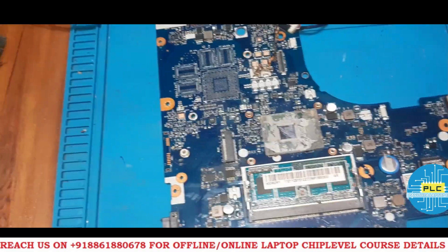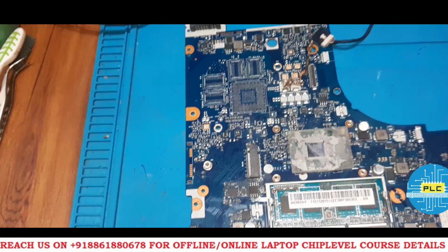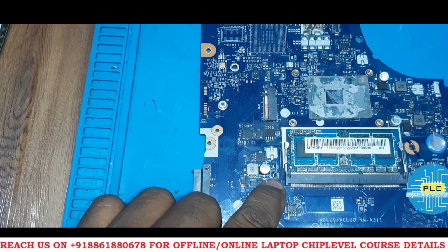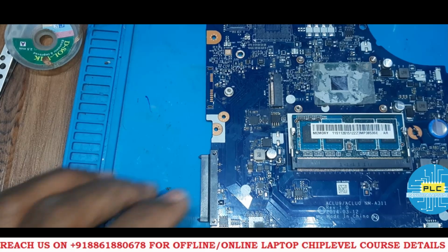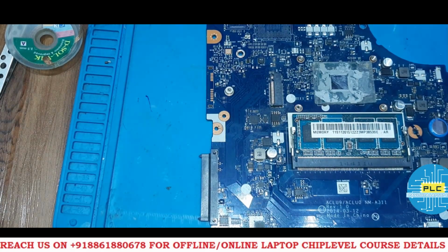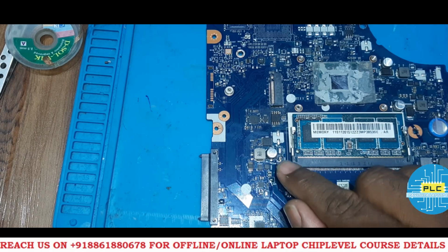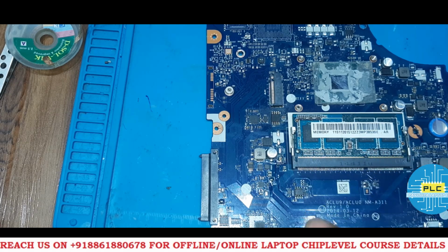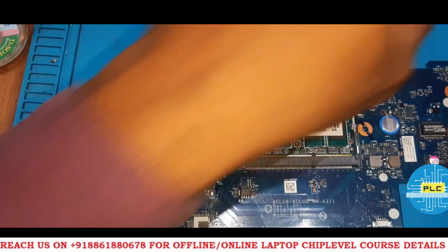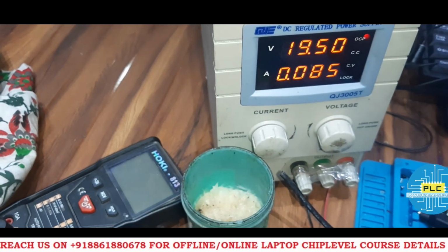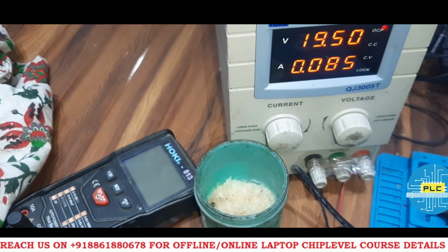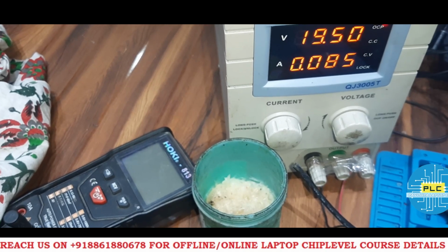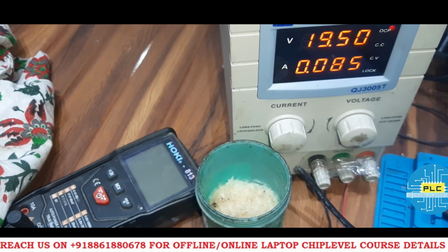Okay, now I'm going to remove the main section, the RAM section. It's 1.2 section, sorry, 1.35 section. Now I removed the very main voltage, that is the RAM voltage. The jumpers are PJ502 and PJ503. It was the plus 1.35 V section. Now I'm going to connect the supply. So what will be the DC amp? See, there is not much difference. It's 0.085. Previously it was 0.086, I think so. It's constant at 0.085 amp.